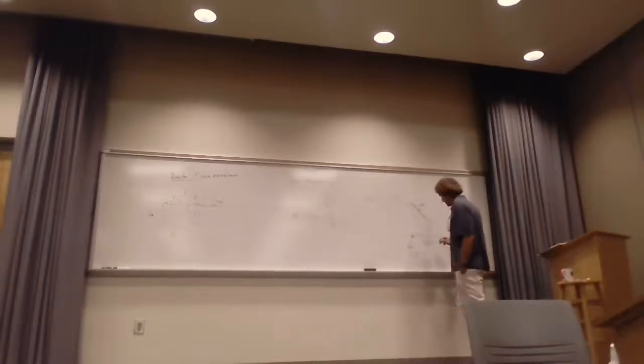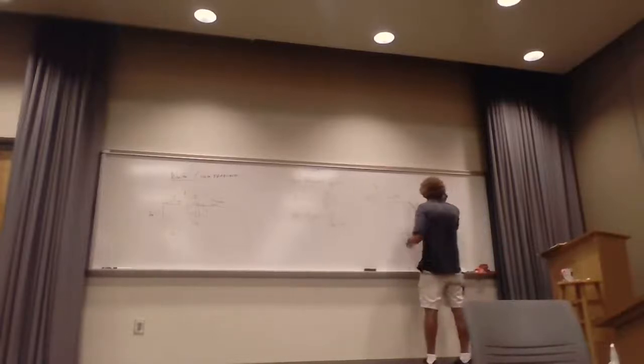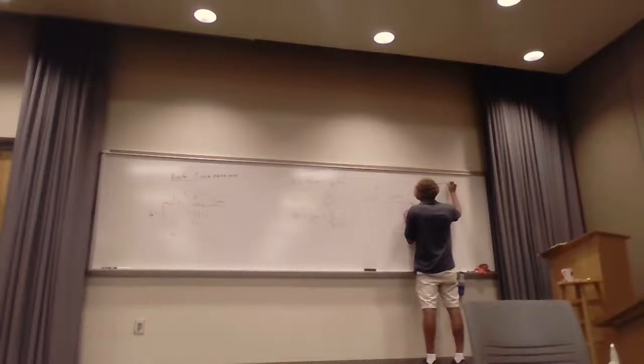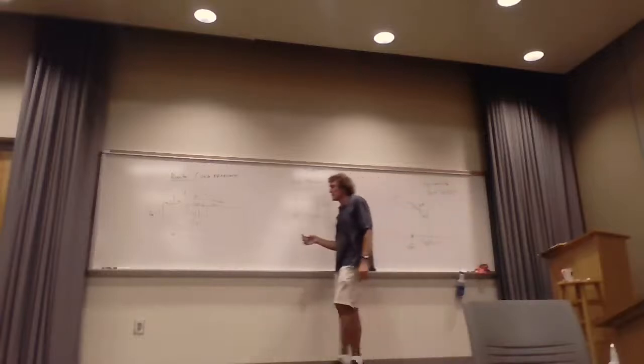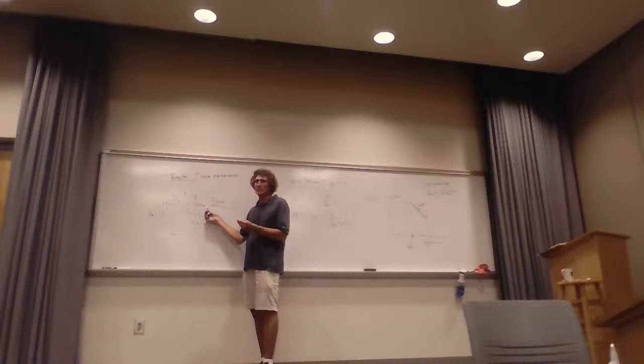And then, and this is the important one, it's going to hit what's called the self-resonant frequency, right here. That frequency, f_SR, is equal to 1 over 2 pi square root of LC. Now that's the L of the lead. Primarily, it's the lead inductance. The internal inductance of resistors usually is not a factor. I'm just leveling with you.